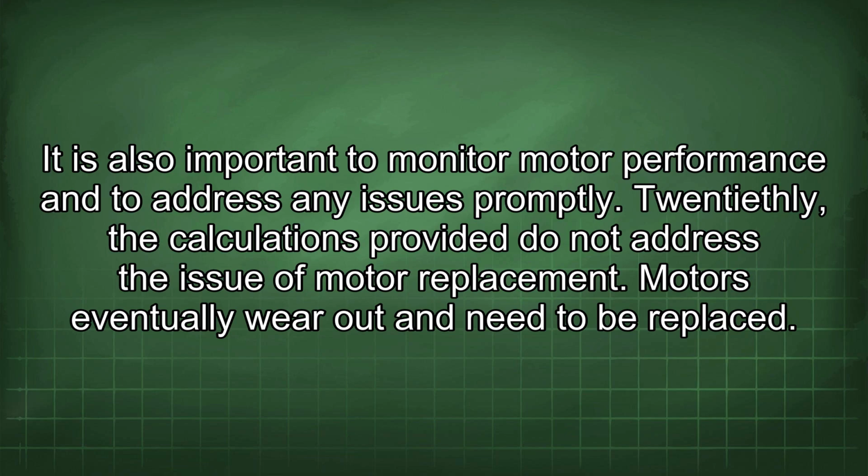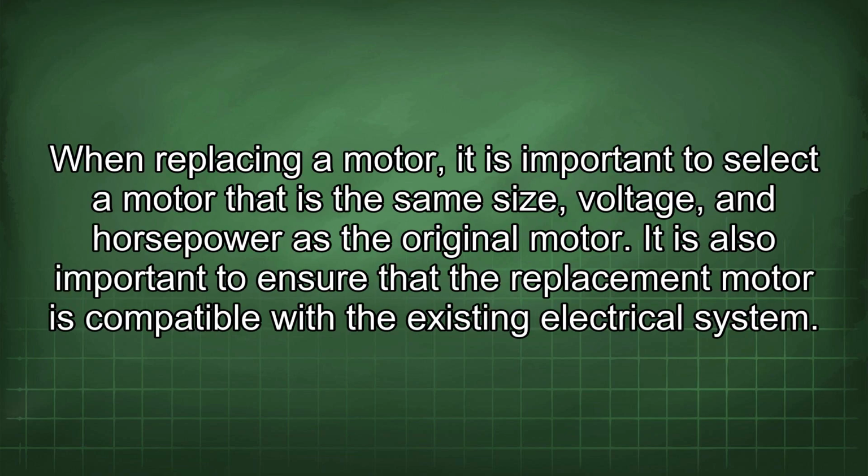20thly, the calculations provided do not address the issue of motor replacement. Motors eventually wear out and need to be replaced. When replacing a motor, it is important to select a motor that is the same size, voltage, and horsepower as the original motor. It is also important to ensure that the replacement motor is compatible with the existing electrical system.